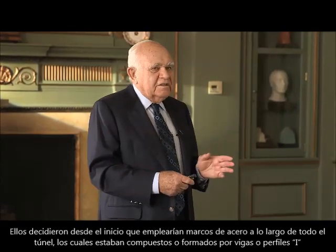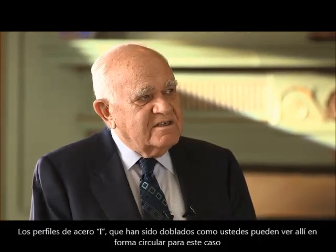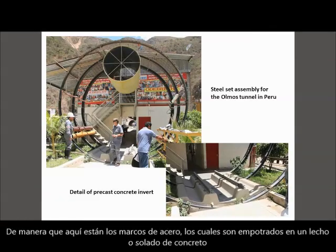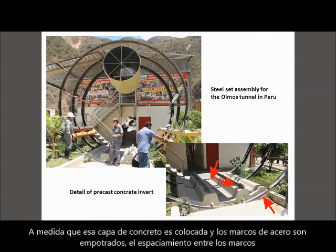They decided right from the beginning that they would line the whole tunnel with steel sets, which are steel I-beams, which are bent into a circular shape in this case, as you see there. So these are the steel sets. And they're attached to a concrete invert, the bottom layer, which goes in first, right along the base of the tunnel as it's mined. And that invert contains a drainage ditch in the center, as you see there, and the ties for rail lines.